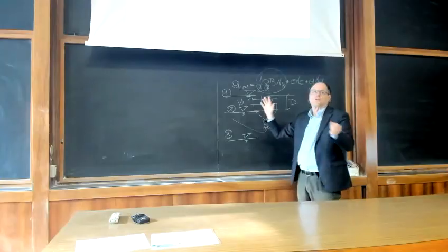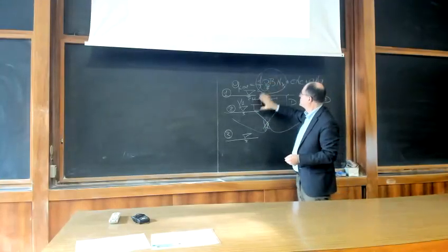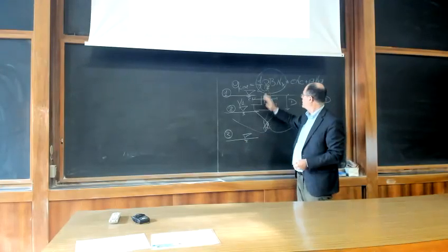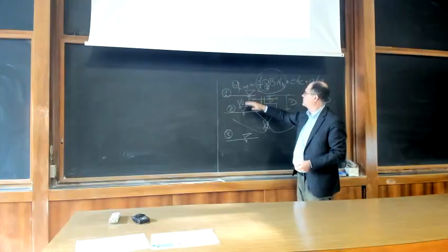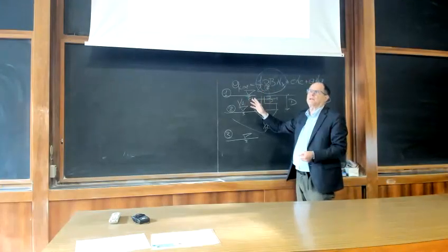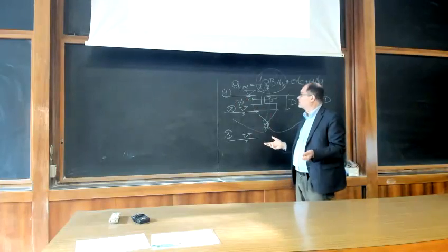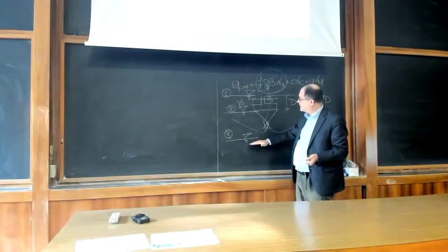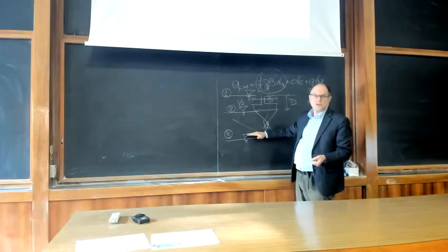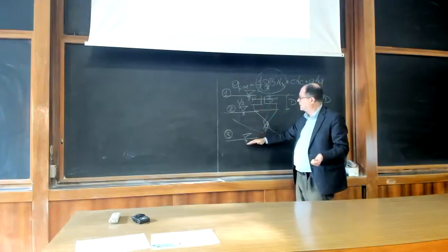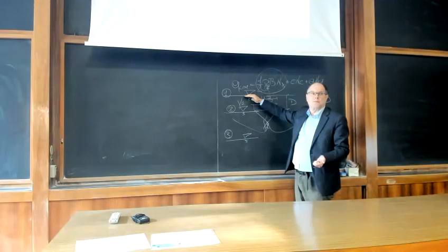and you have also to consider that if you have a footing and you consider that, well, my groundwater table is well below, so I consider gamma saturated or the natural gamma, not a gamma dash, you end up with a limit pressure which is a specific value. Then the water table rises up for any possible reason, to here.